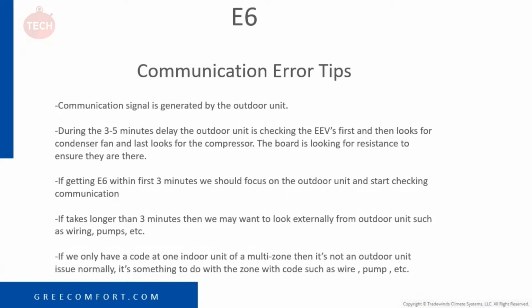The board is looking for resistance to ensure that they are there. If getting an E6 within the first 3 minutes, we should focus on the outdoor unit and start checking communication, which we'll get into showing you how to do that here shortly.